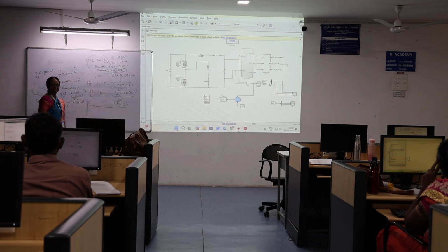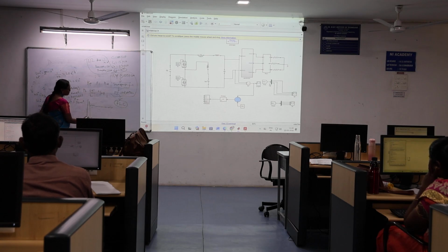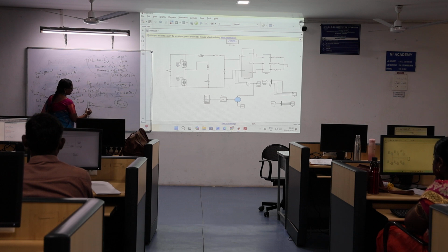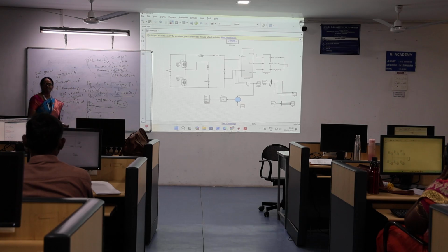So I have to find out this time period, and from the time period I have to design my proportional gain, integral gain and all. Here I have to find out my rise time, my fall time, and my settling time. Then finally it is settled to some value. For example, we kept it as 320 volt and it is settled to some 320 volt. That steady state error is 1 volt. All this we may obtain from our closed loop condition.